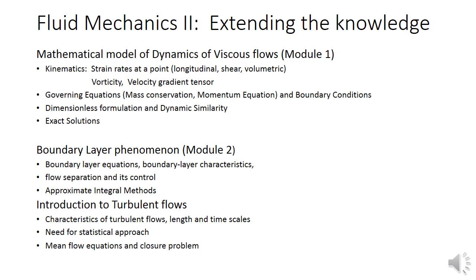Then there is another very interesting point, a concept of dimensionless formulation, which leads to a natural consequence, dynamic similarity. So here we talk of two different flows which may be geometrically similar. What are the conditions under which the flows themselves will be dynamically similar? These are the questions that will be addressed in this section of the syllabus: dimensionless formulations and dynamic similarity. These are very important from the point of view of model testing in the case of fluids.